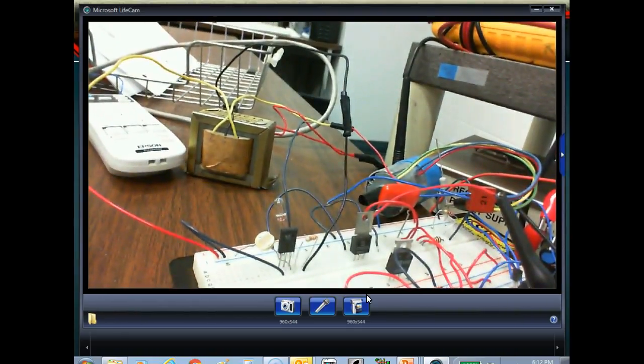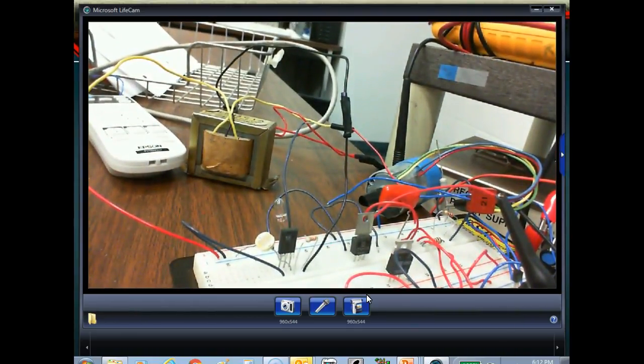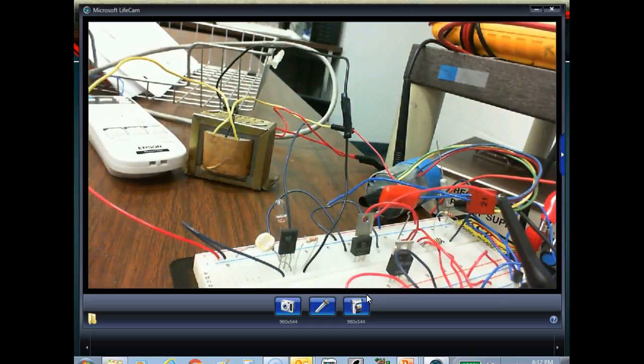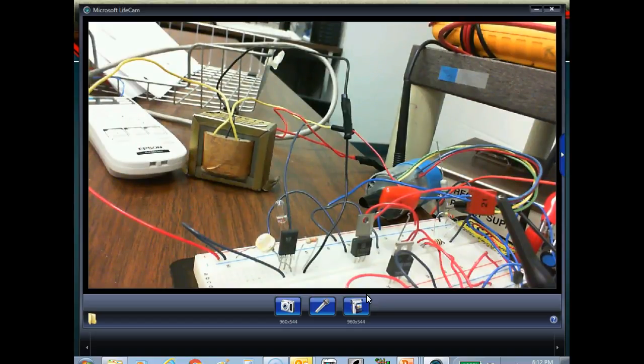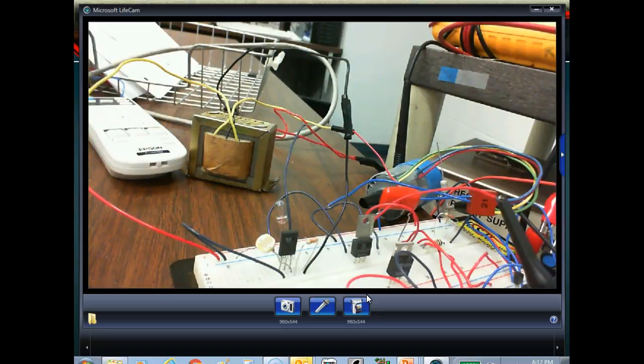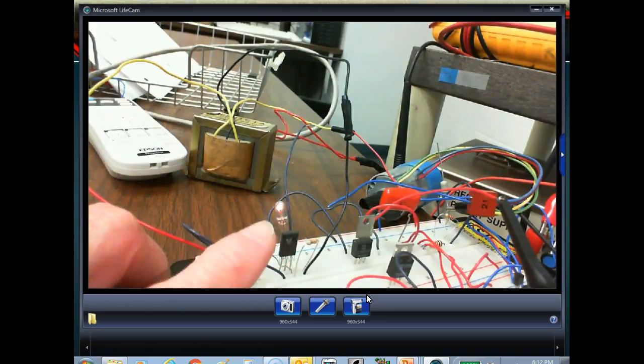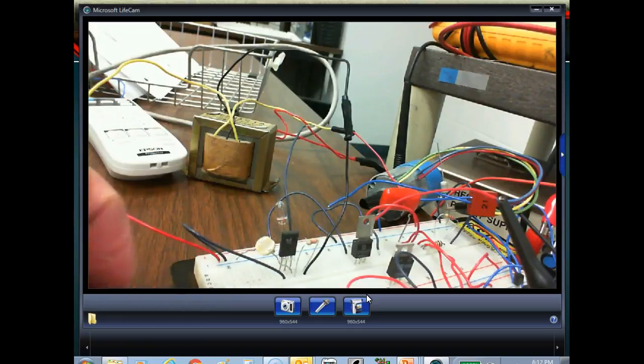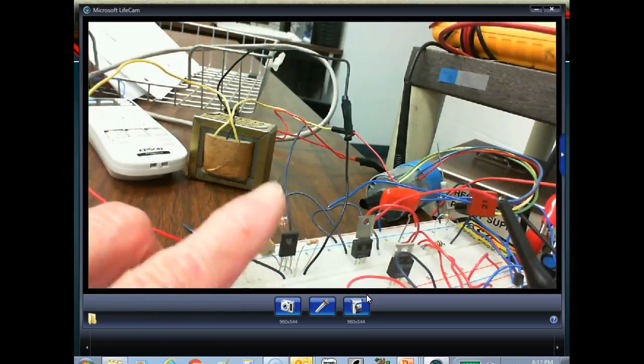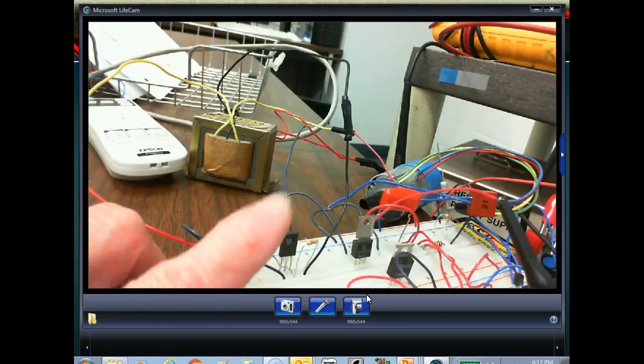So yeah, I could control my light. You could dim your incandescent lights with a big rheostat. But how big would it have to be to run a 100-watt light bulb? You understand? A 100-watt light bulb requires about 1 amp to run. So very, very electronically, I can control it with this. If I tried to run this bulb with this little old tiny photocell, I would burn it up, right? You understand? But all this guy here is providing is gate current.